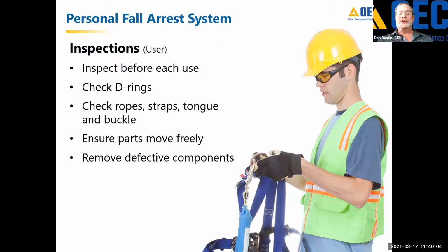Considering as the user, you are expected to inspect that harness prior to the time you put it on every day, you become the competent person after you have been trained on that harness. They tell you what to look for. So it's inspected before every use. If you take it out of the job box or it just came out from the tool room at your company, take a look at it.